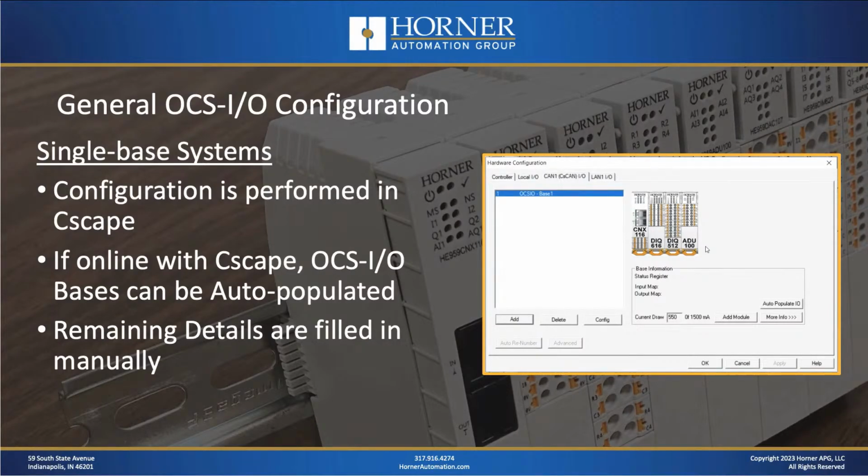Now, configuration is performed from Cscape, and it can be done completely offline. You don't need to have your equipment present in order to do configuration of OCS-I. However, if you do have your equipment and you can set up Cscape, your OCS, and your OCS-I to all be connected and online, then the bases can be auto-populated in Cscape, which will save you some time. And then once the base has been added and auto-populated, you'll just have to fill in some remaining details.